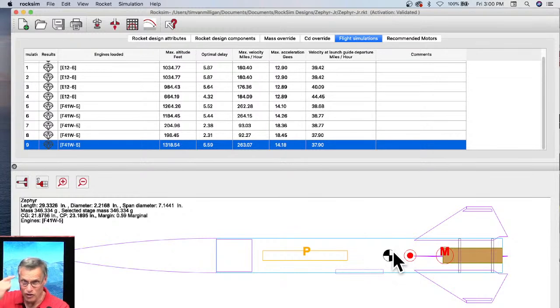But human intelligence is pretty good, because before we ran it with a margin of 0.19. Now we're at 0.59, and we did 1.23. And so you can kind of see that somewhere between too close and too far is an optimal. And you can kind of zero it in probably within like 5 or 6 simulations, but you have to do them manually. I guess if we had artificial intelligence, that could probably help too, but there's a lot of variables involved here.